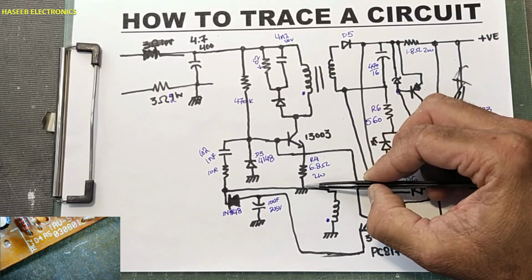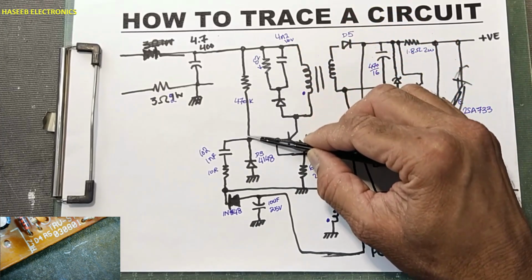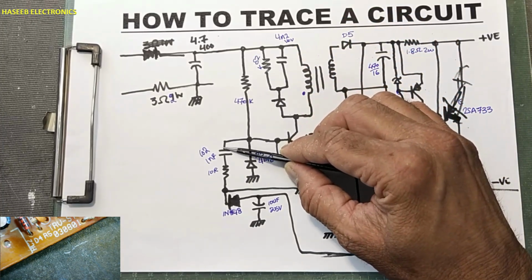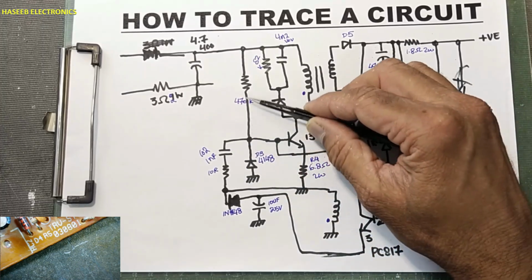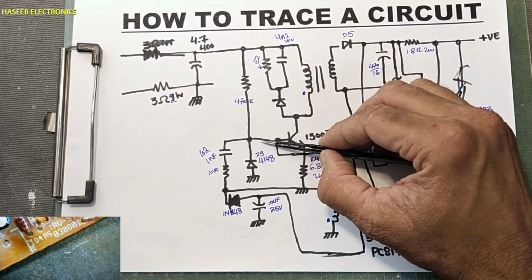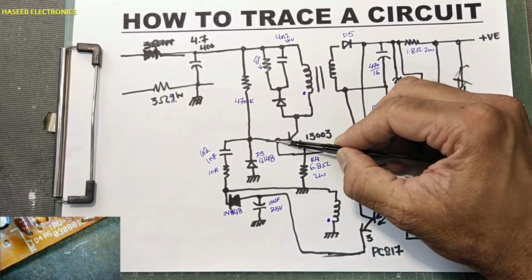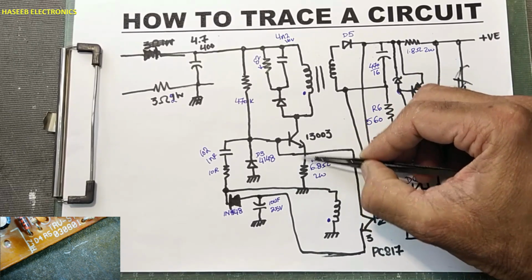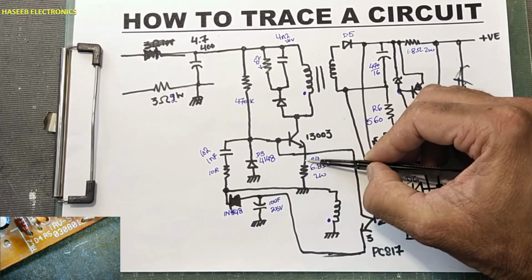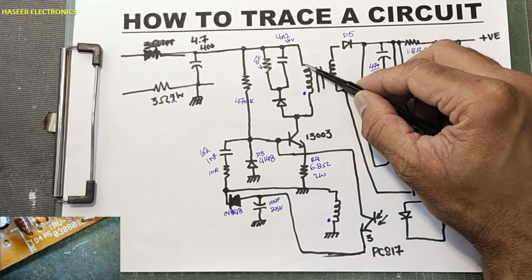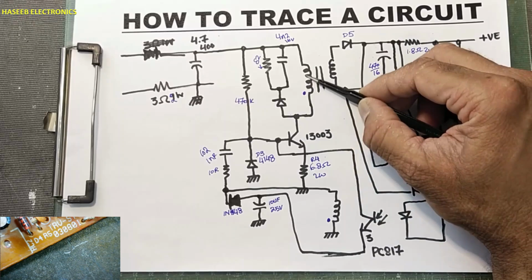It is low, and here this positive voltage will come and it will start to charge this capacitor positive, and this side is grounded. When this current will flow, the voltage level will increase on the base. Base to emitter current will flow. When this junction will start to conduct, high current will flow in this zone. When emitter current will start, collector current will also start.